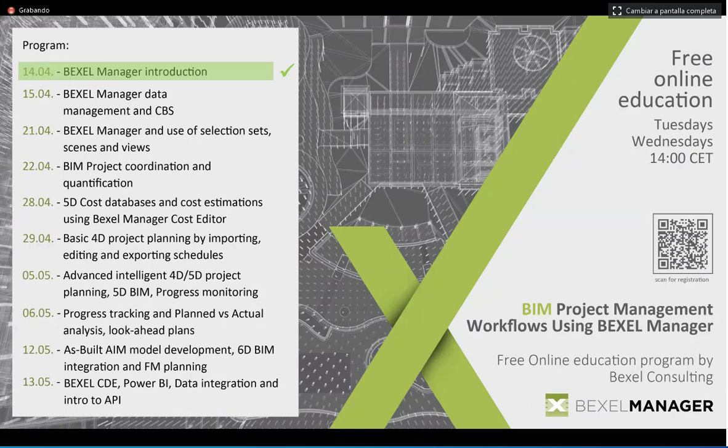So you saw quite a large building, quite a large project with a lot of reinforcement elements, which are imported from IFC files. So I repeat, if you want to see your rebars as 3D BIM model elements, you have to use IFC. Otherwise, if you're using BX3 files exported from Revit, these are going to be, let's say, optimized in order to make the model much easier to work with.